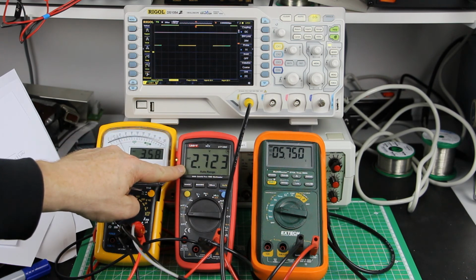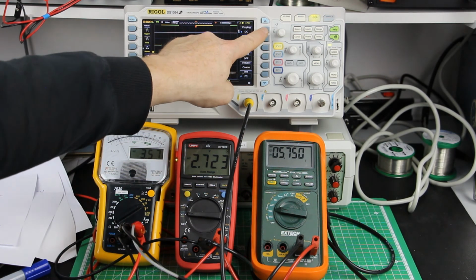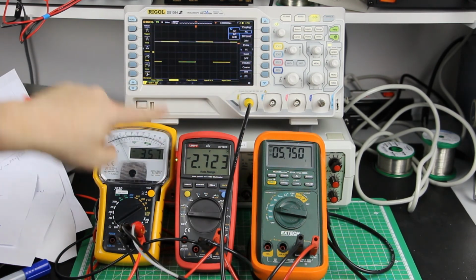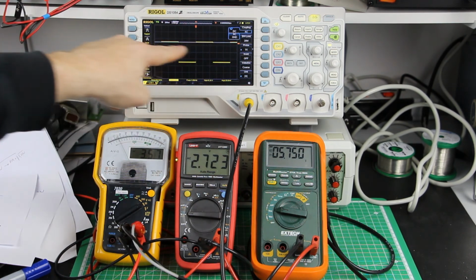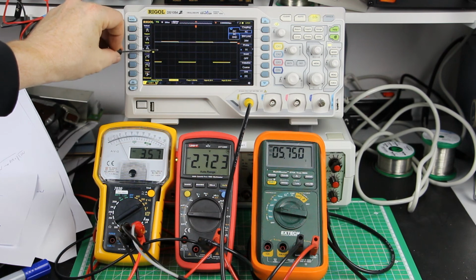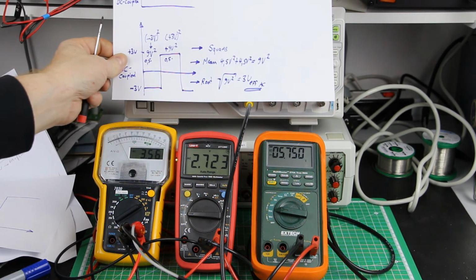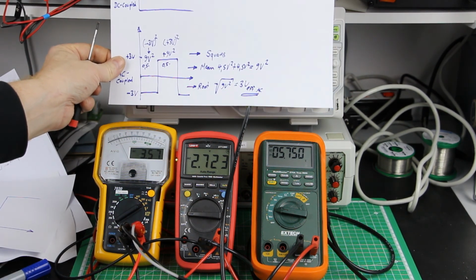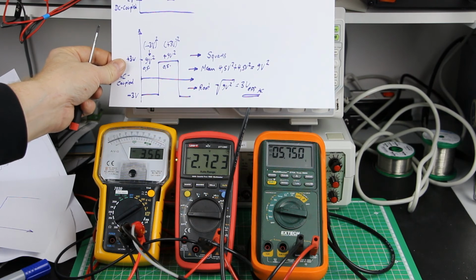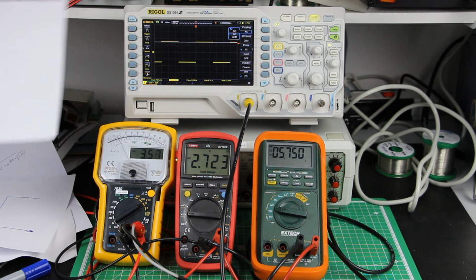Now, can we simulate, or can we get the reason for the difference? Both of these have a capacitor in front of their measurement circuit, and the capacitor does this. It measures from an AC coupled signal, which gives us, as we know, a different value, which should ideally be exactly 3 volt effective true RMS AC coupled.